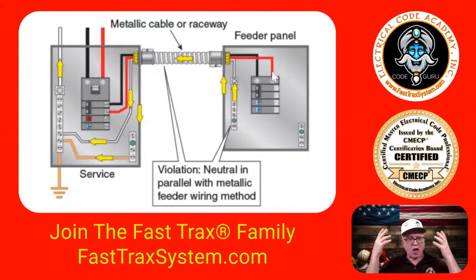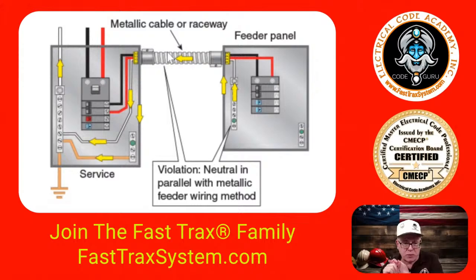Let's say probably 100 amp rated. So in that case, you're not going to be using liquid tight flexible conduit. You're not going to use flexible metal conduit because they have limitations on the amps, and that would be a problem. So that's not going to be used. This is not MC cable because I see no separate equipment grounding conductor, and you can't use the MC armor as an equipment ground in larger sizes.